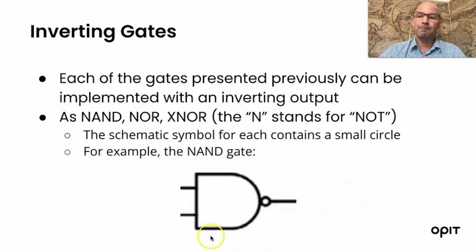And this is what it looks like. The AND gate, you remember, has the two inputs, A and B, or I0 and I1. And remember that with the AND gate, both of the inputs must be 1 for the output to be 1. But with the NAND gate, it's actually the opposite. Any of the inputs that are not 1 and 1, for example 0 and 1, results in 0, but the inversion of that becomes 1. Okay, and we'll see the power of the NAND gate in some examples in a few minutes here.